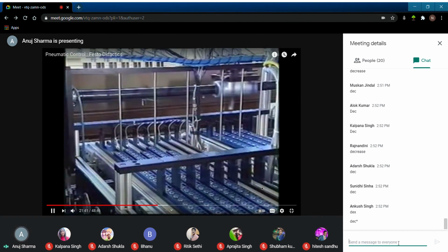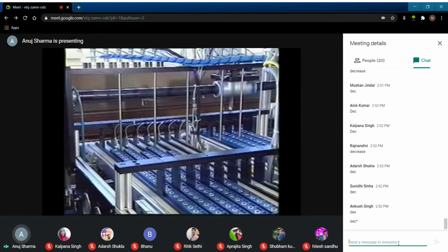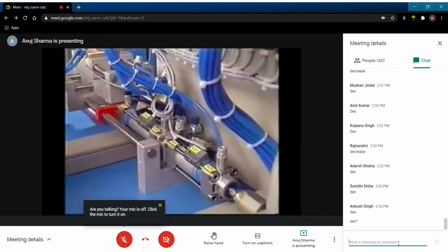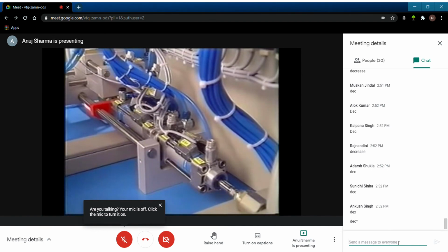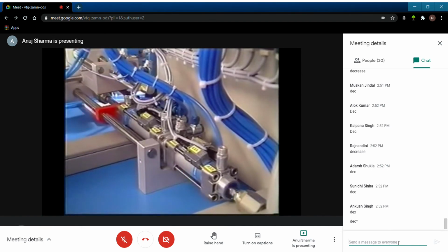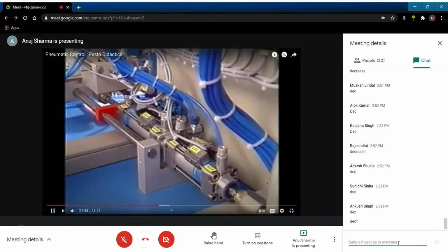Multi-positioning can also be achieved using cylinders, in this case with valves and multiple sensors. Another form of multi-positioning uses two double-acting cylinders joined together. If the cylinders are of different length, this design is capable of achieving 4 different positions.